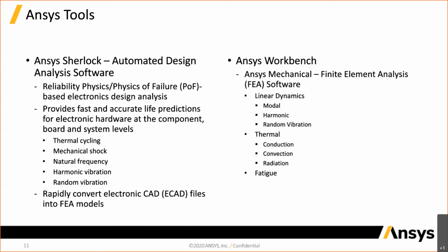You define the PCB stack up, give it all its different layers, layer count. It'll automatically determine percent copper coverage on each layer. It'll predict the modulus of that PCB, and it'll also make up the moduli for all the components based on die size, lead style, and that type of stuff.